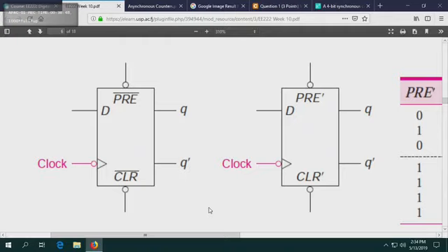Remember, I think most of you guys were using Logisim. One or two people used Circuit Maker, right? For Circuit Maker, they use the preset and the clear. For Logisim, when I came to mark you, I said, I want to look at the unused state. Or the tutor said, I want to see the unused state, 1, 0, 1, 0. So you went and clicked on the flip-flop itself. What you're actually doing is using the preset and the clear line in a software version of it. That's what you'll have to do if you build it in hardware.